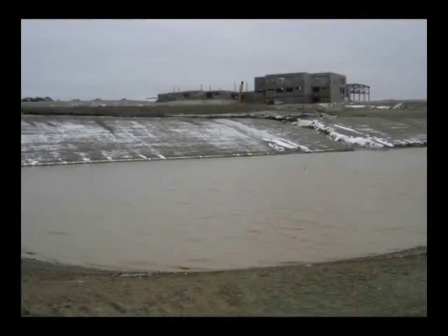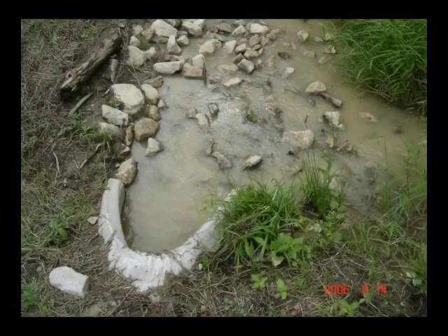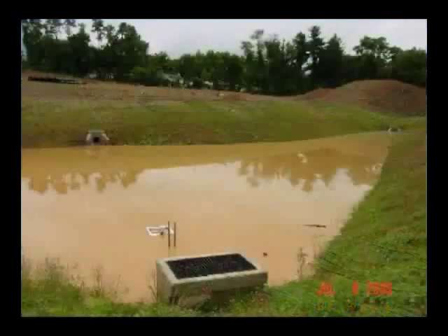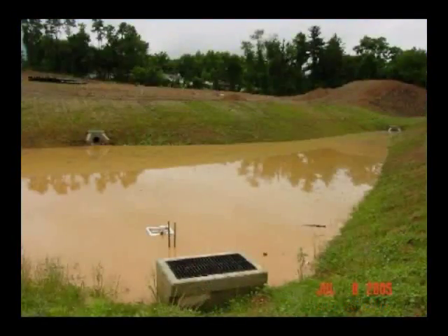Sedimentation basins are common sediment controls used on construction sites to trap sand and large silt-sized sediment carried by stormwater runoff. In general, basins are not effective in removing clay and fine silt. For effective sediment control, basins should be at least 4 times as long as wide, with the inlet and outlet at opposite ends, and the outlet at a higher elevation than the inlet.